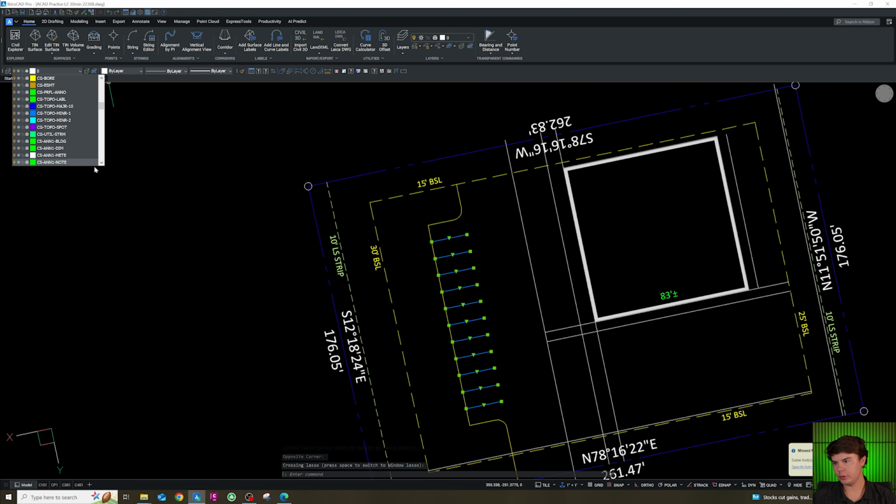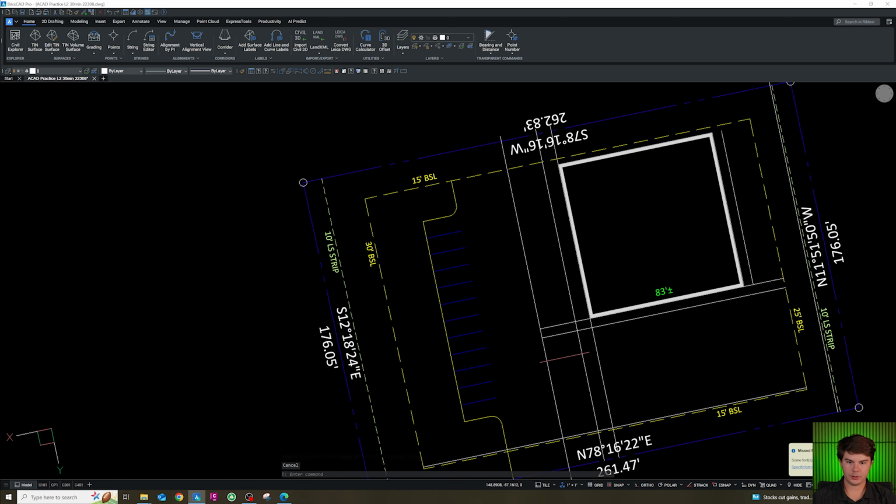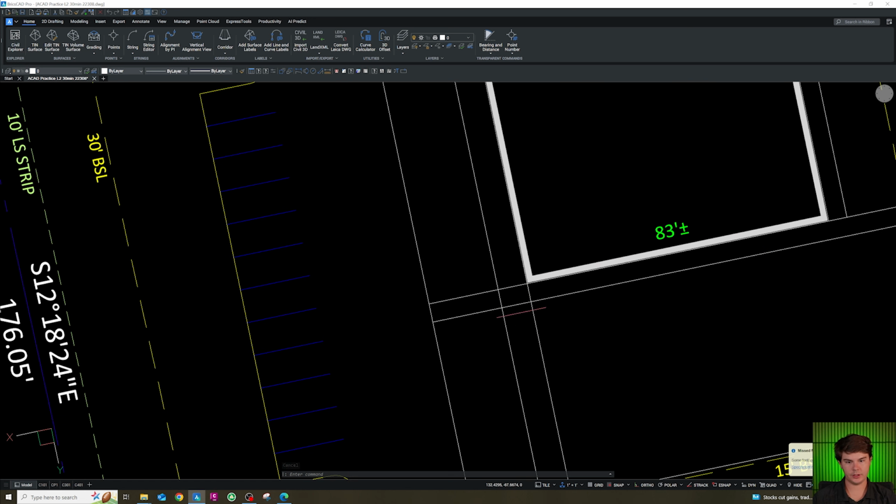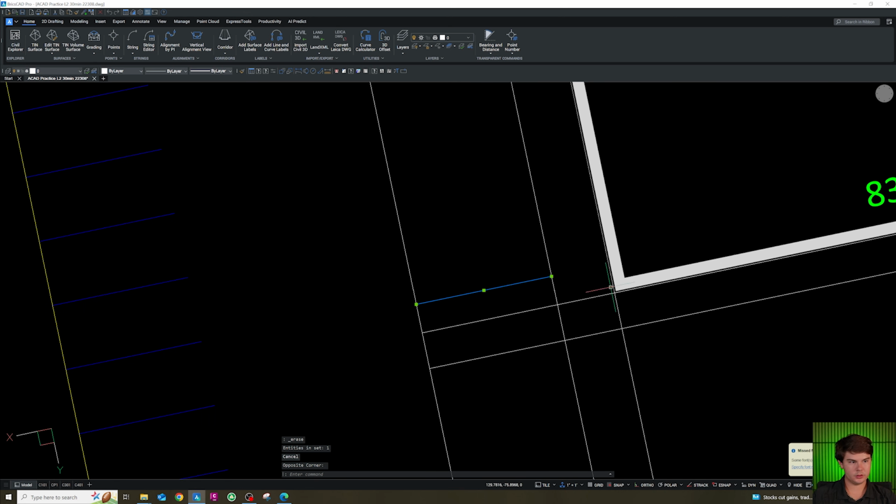CS site stripe layer. Okay. Now we're gonna have some parking right here. Typically we do a 9-foot island, so I'm just gonna offset 9 feet from here, and I'm going to trim this away. This should be 19 feet long, and it looks like we have a handicap spot